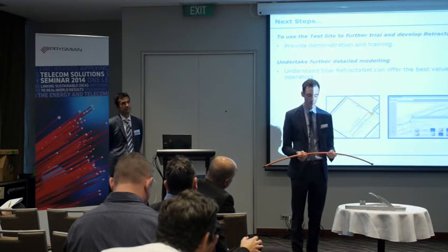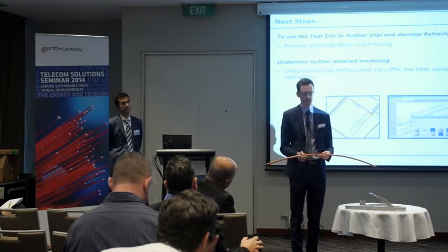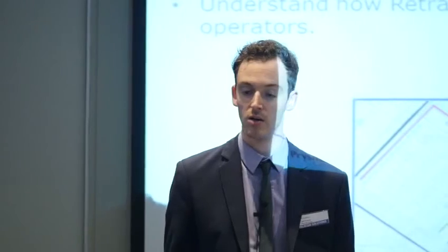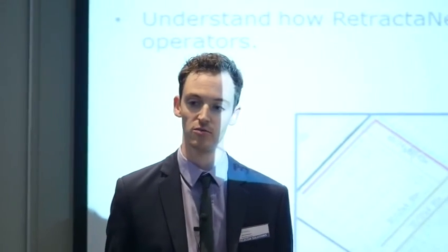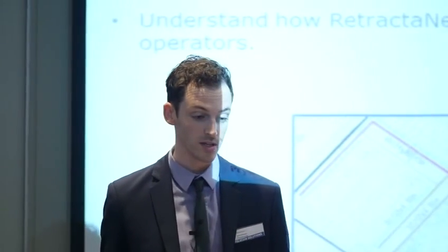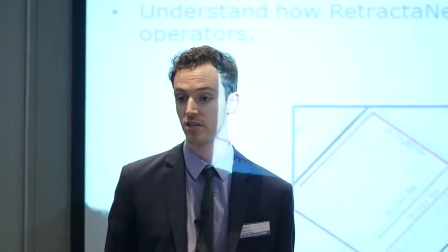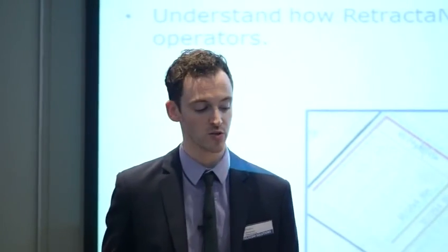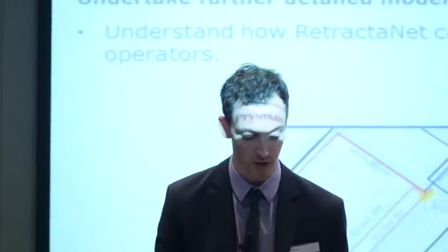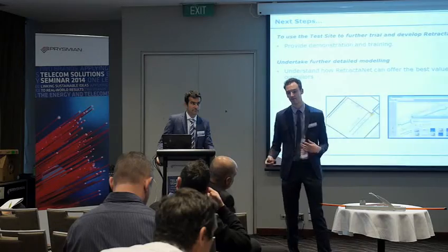Another thing, we could permeate the sheath with an anti-termite chemical, which has been known to repel termites. So that's another option if we didn't want to go down the nylon route. But I think nylon would work quite well, with the reduced friction during installation that it gives you. So that's what we're really talking about: adapting the solution we know works in Europe to the Australian climate and the Australian challenges.